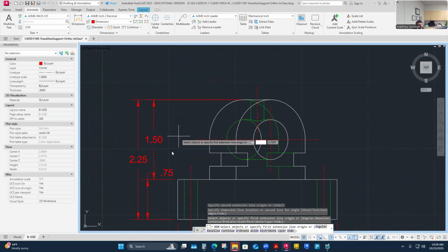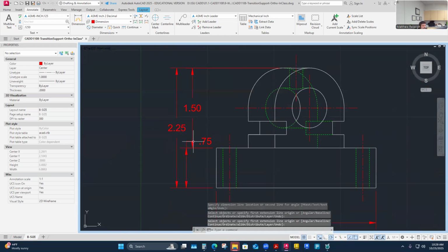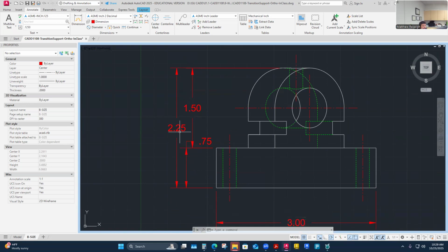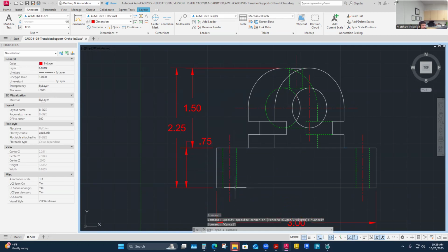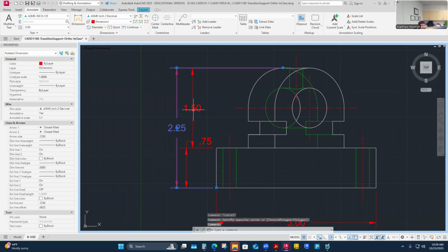And so my argument here is that this is a scenario where I'm chaining these together. That means if this is off, then this is going to be off. I would need to establish which one is the most critical. Could you just have the top surface of that bottom plate be your datum? Yeah, I think so. You could use this top surface as one. And then this dimension's going from this surface down and this surface up. So you've moved your bottom surface datum into this top surface. Yeah, I think that's legit. And in that case, you would leave both of these as is, and maybe this one becomes a reference dimension, and these both are critical holes.